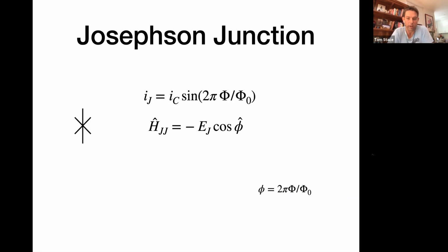They're one of the family of superconducting circuit elements like capacitors and inductors, and they're characterized by a very specific constitutive relationship, which is the top one there. That is that the Josephson current is a function of the flux linking the junction, and it's not just any function, it's a nonlinear function. It's a sinusoidal function of that flux. So they're interesting devices because they're extremely nonlinear. And so people have used Josephson junctions in all sorts of ways to fabricate really large nonlinearities in superconducting gadgets.